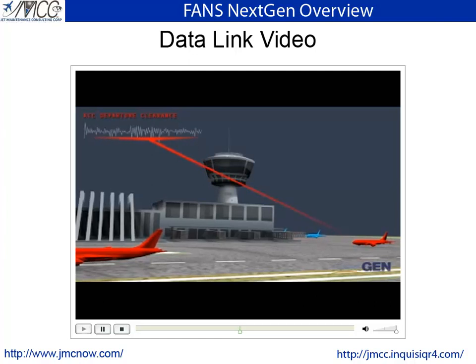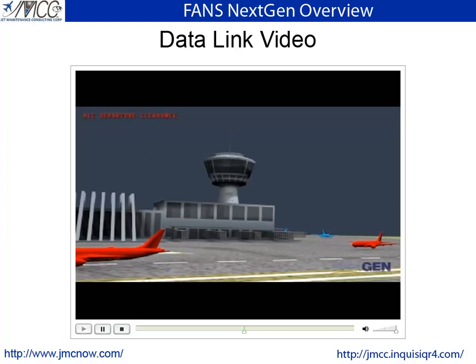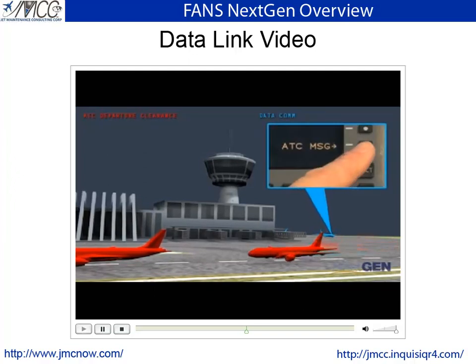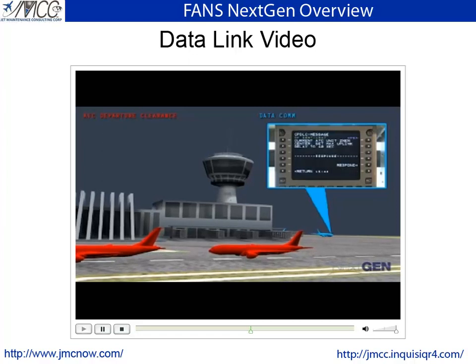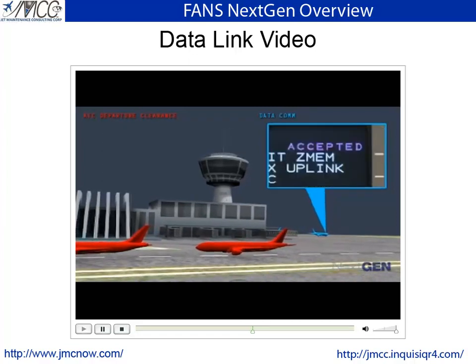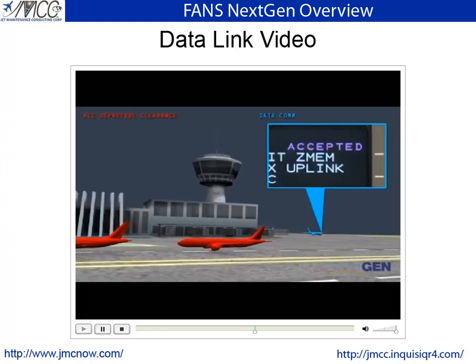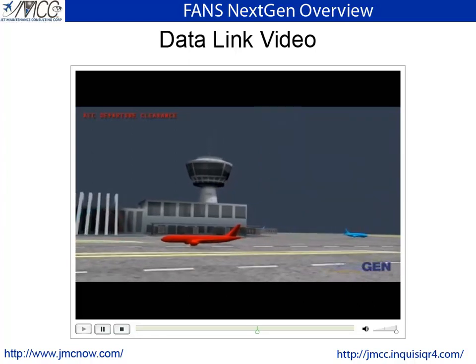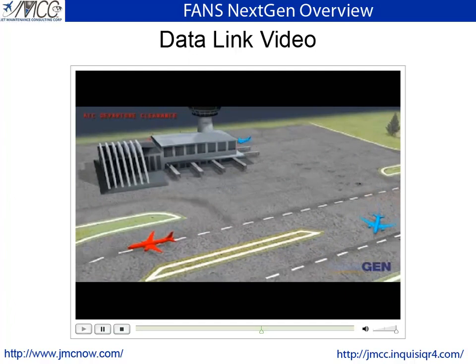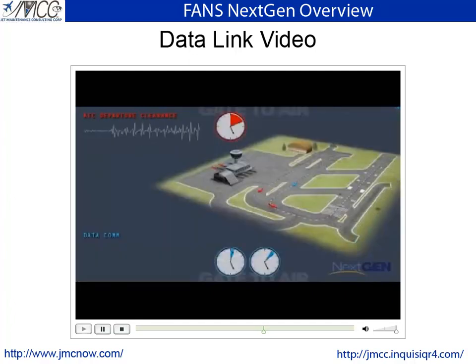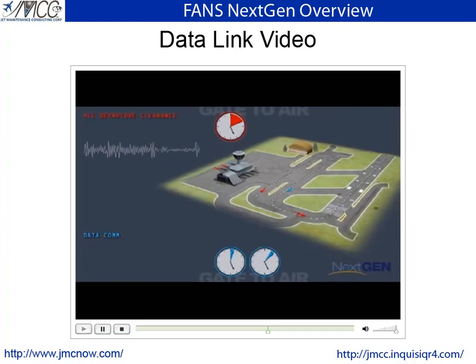J60 after Newell. If there are reroutes to deliver, the process bogs down even more. With the Datacom-enabled plane in blue, the controller sends digital route information directly to the plane's Datacom receiver. The pilot simply reads the text display and presses Wilco for Will Comply. Then the instructions are loaded directly into the onboard computer system. This takes only seconds. When we look at this process across the operation, the time savings are significant.